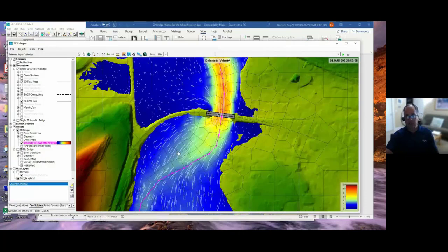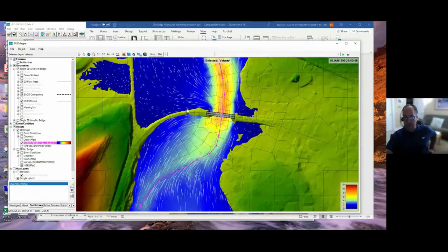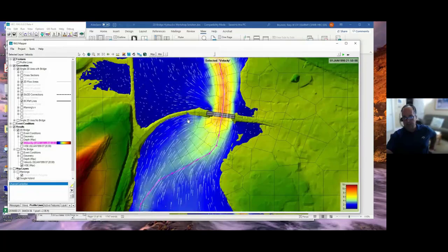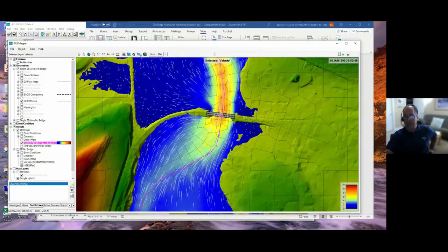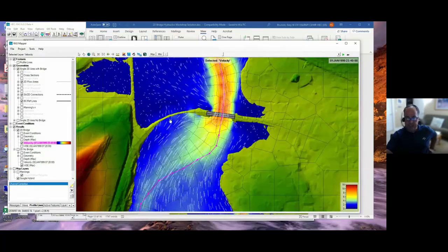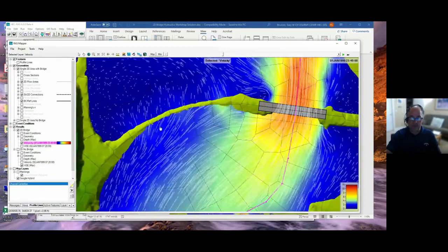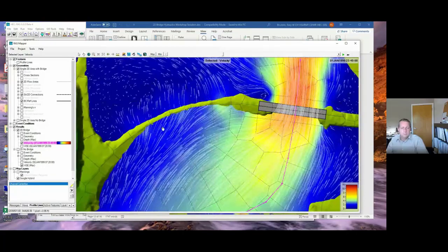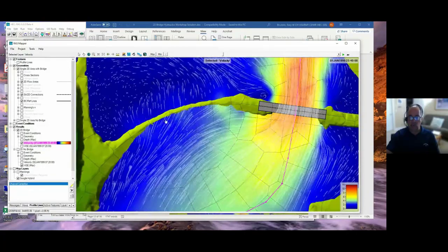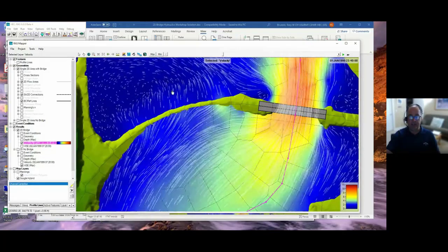Okay. So here at this point in time, you can obviously tell this is not being overtopped, right? Because the velocity is all going this way. But as I increase this and turn on the tracers again, now there is some overtopping. Let's see what's happening here. Remember, these faces right here, this face is wet, right? On the upstream side. That means water is higher than the face, because the face is wet, and it's dumping water into the downstream cell.